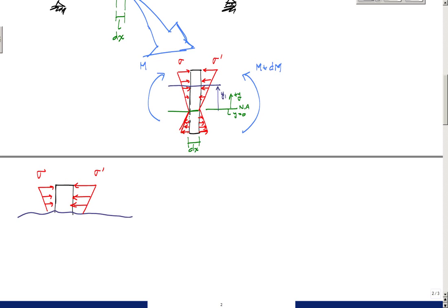What I have to ensure is that even though these sides are unequal, I have to have equilibrium. So you would suspect that there is something else happening here, which happens to be the shear between layers, right? This tau. If you could see a 3D view of this side, this line right here really represents, in 3D, a surface area.